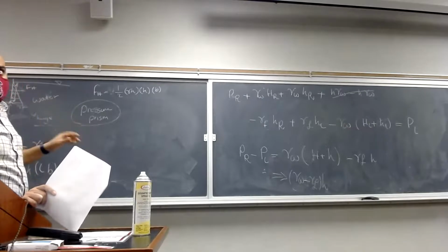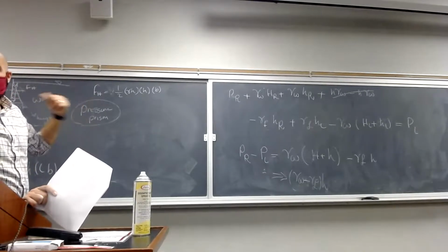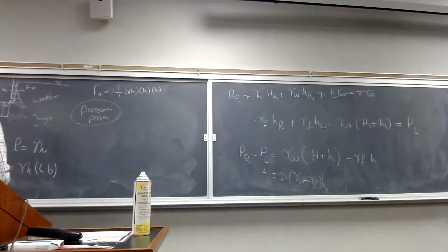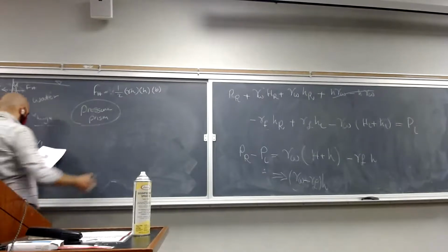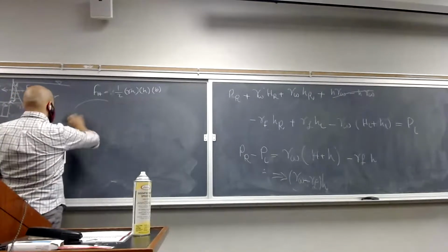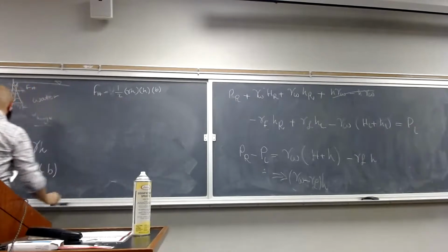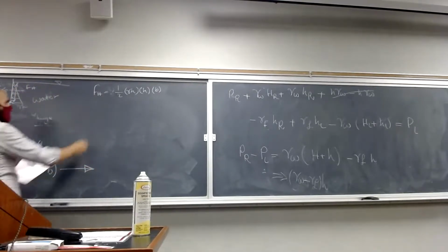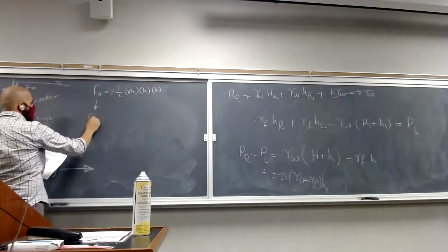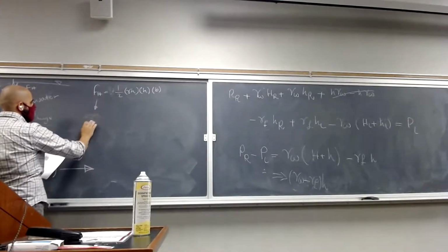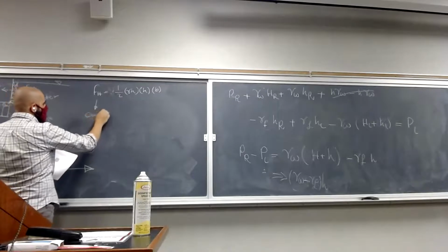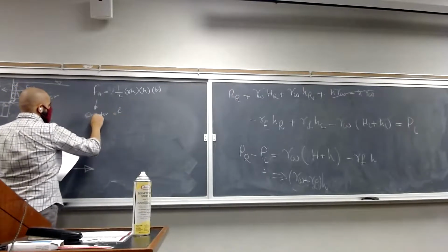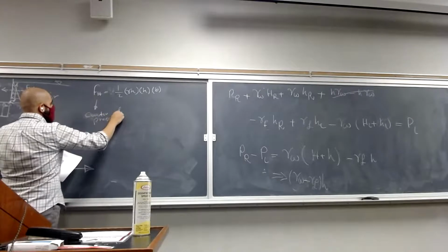So we have the forces that are going to create the moment, right? The vertical force passes through which location? We already know that the horizontal force passes through the center of pressure, which we talked about at the beginning of this lecture, and we have to find that location.